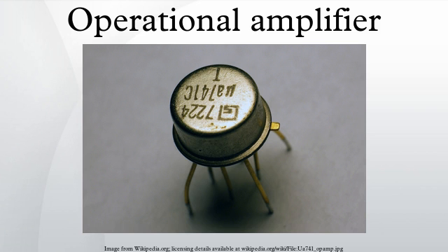Input offset voltage creates two problems. First, due to the amplifier's high voltage gain, it virtually assures that the amplifier output will go into saturation if it is operated without negative feedback, even when the input terminals are wired together. Second, in a closed-loop, negative feedback configuration, the input offset voltage is amplified along with the signal, and this may pose a problem if high-precision DC amplification is required or if the input signal is very small.